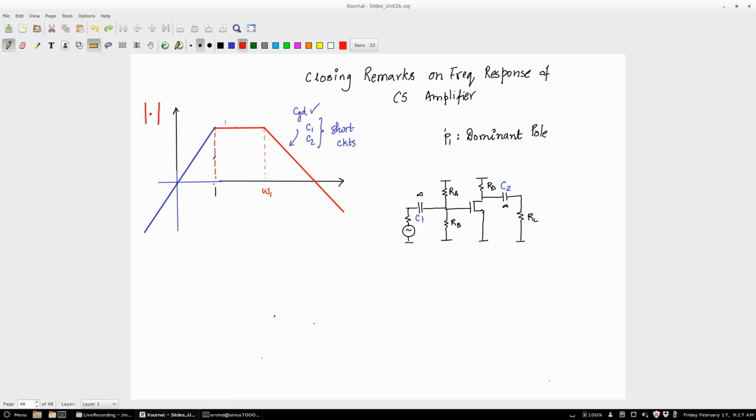So maybe what I can do, to be clear, because otherwise we are not engineers, is plot this and mark this frequency. What's the name of this frequency? I call that the omega corresponding to the decoupling capacitors, the decoupling. What is the value of that? If this was R and C1, roughly what is that? That is 1 by RS C1.